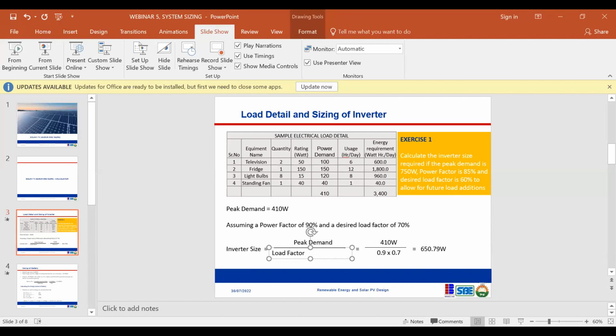If anyone has a question, please feel free to ask. So in the end, this slide, the power factor. Maybe for this system it is 90%, but I think for most systems it is 80%. This is just an assumption that it is 90%. You can use 80%. But in reality, have you tried to measure the power factor of your building or of your house? The reason I'm saying this is that we also have to compare the reality and design. For design purposes, please use 80.